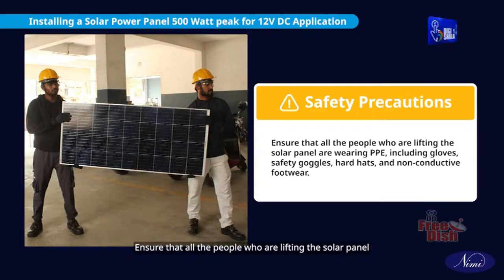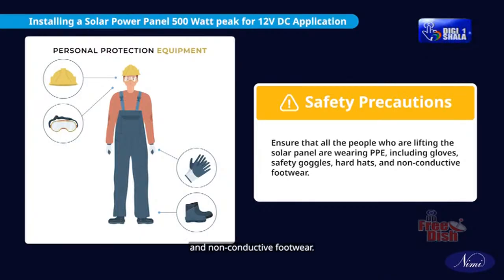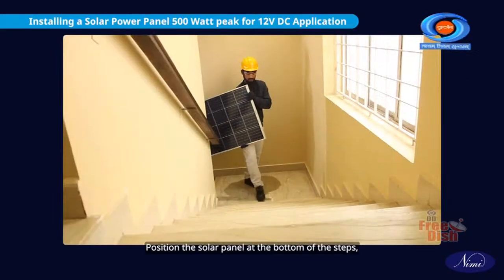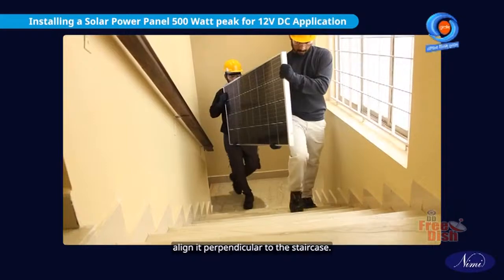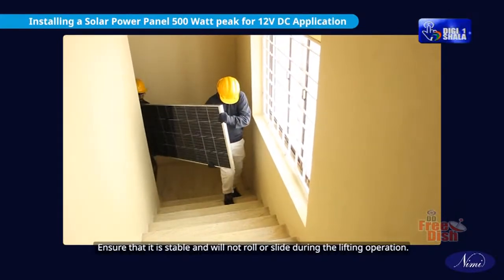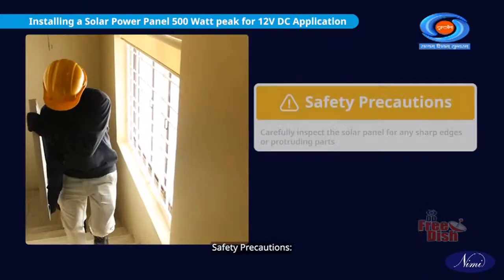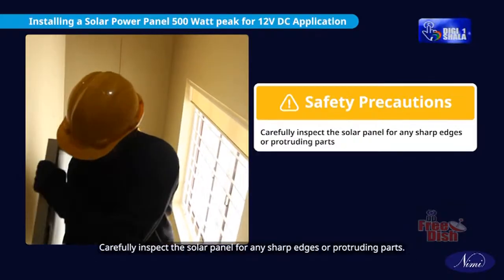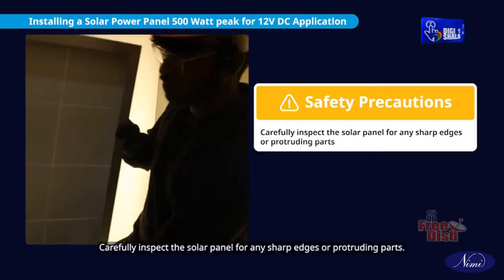Ensure that all the people who are lifting the solar panel are wearing PPE, including hard hats, safety goggles, gloves, and non-conductive footwear. Position the solar panel at the bottom of the steps. Align it perpendicular to the staircase. Ensure that it is stable and will not roll or slide during the lifting operation. Safety precautions. Carefully inspect the solar panel for any sharp edges or protruding parts.